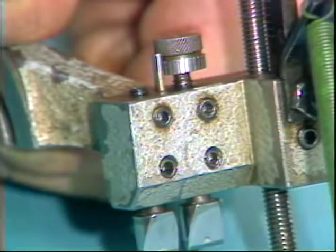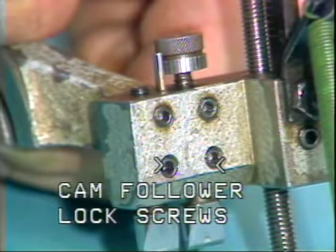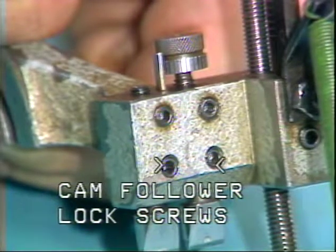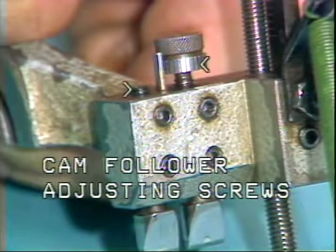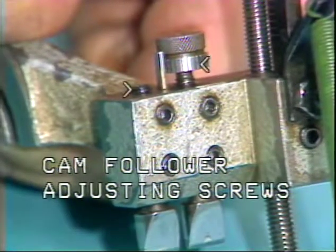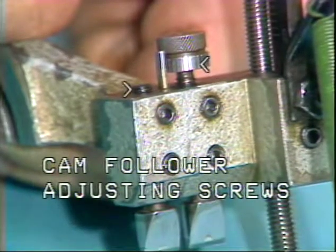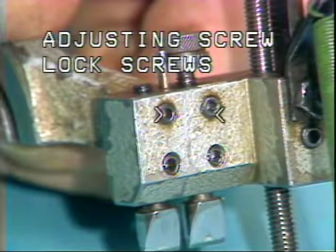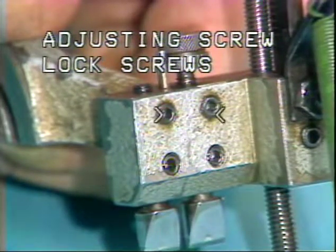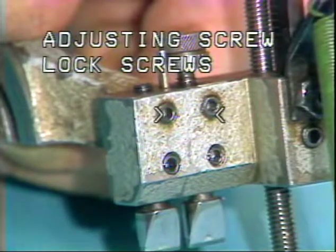These are the cam follower lock screws. They are loosened before adjusting the cam followers. The cam follower lock screws are also loosened to remove the cam followers. Located here are the adjusting screws for the cam followers. Turning these screws will position the cam followers. Just below the cam follower adjusting screws are the adjusting screw lock screws. Before adjusting the cam followers, both the adjusting screw lock screw and the cam follower lock screw must be loosened.